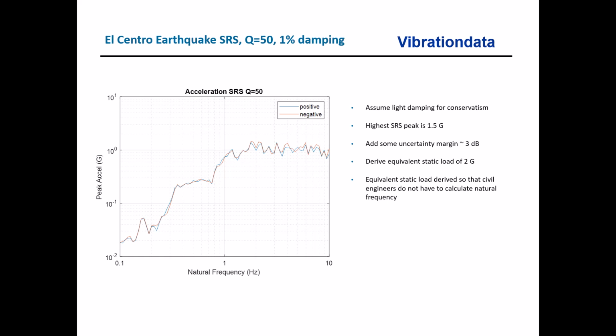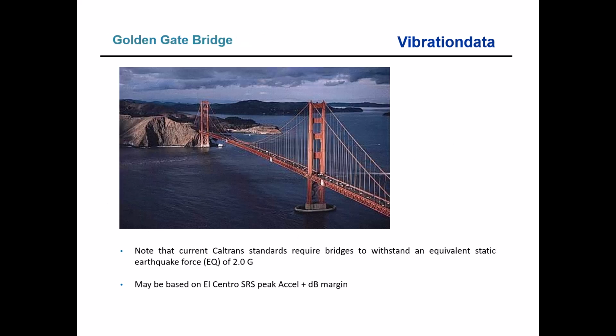Now, it's interesting to think about the damping. I was very conservative with 1% damping. For a large civil engineering structure, if it's just a light wind and ambient type of day, then 1% damping is probably pretty realistic. But in an earthquake, where there could be joint slipping and cracks in concrete forming, the damping goes favorably upwards in the case of a major earthquake. So for us to take El Centro and just say 1%, that of itself is a layer of conservatism.